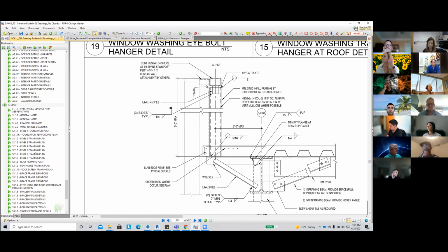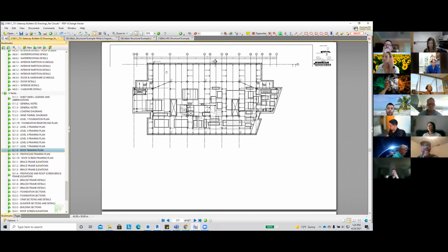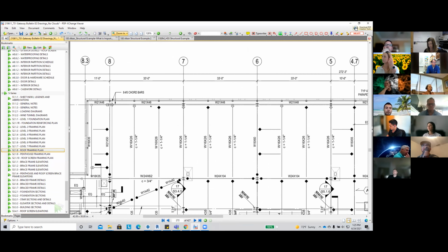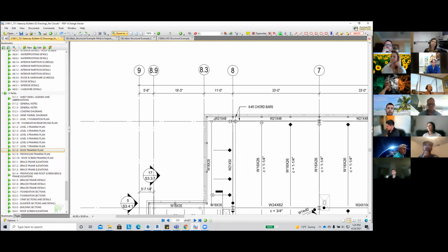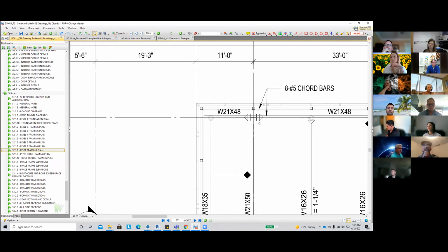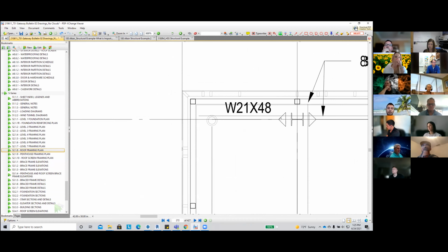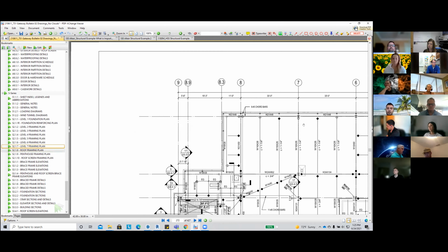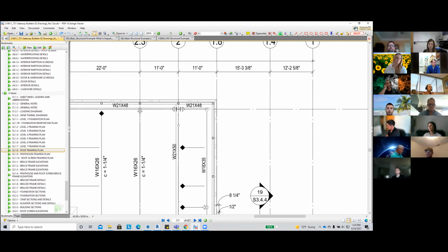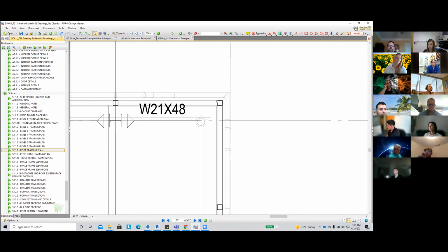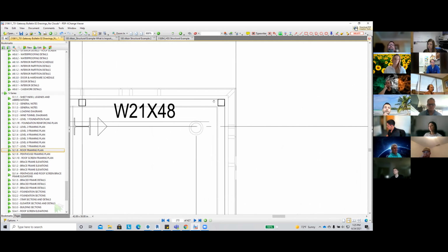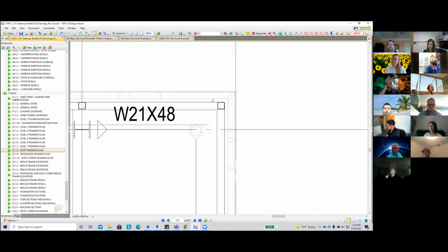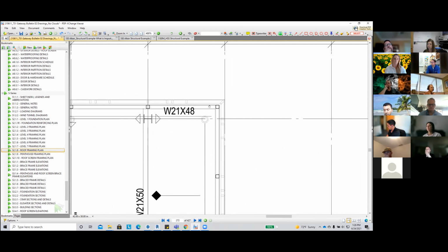Right. Yeah, so it would show on the framing. So if we go to the roof framing, we would actually see the tube. So I guess it would be a matter of laying out from this center line dimension, which is grid A, doing maybe a 2-foot offset and seeing if it lands for this tube, and then offsetting an additional dimension, or dimensioning from the tube to the back of system, making sure that's 3 inches. So that's how I would verify.